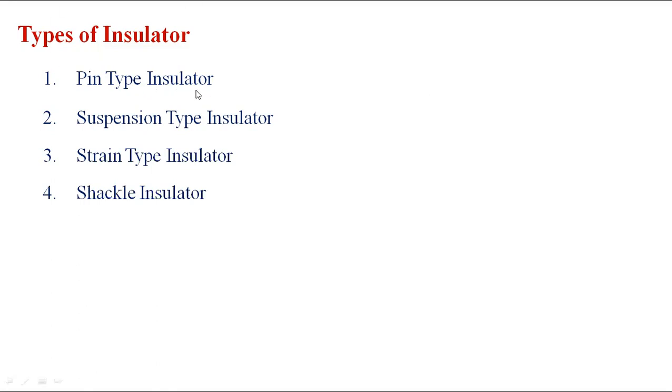The pin type insulators are used up to 33 kV. That is, for both transmission as well as distribution purpose up to 33 kV. Beyond 33 kV, economically it is not satisfied, that is, the cost is increased and the size of the insulator is also increased.